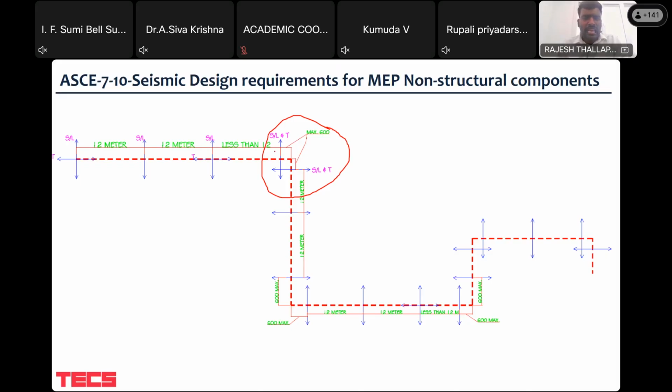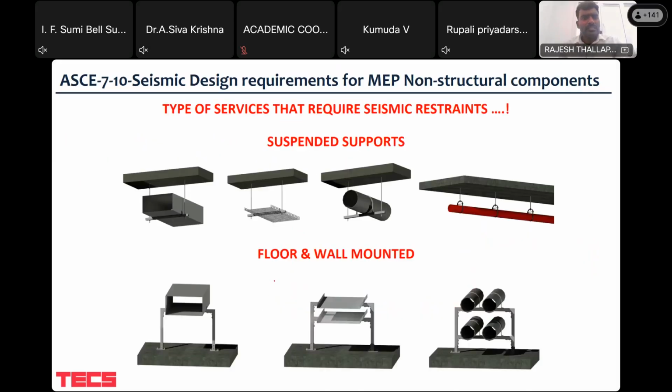So that's the reason any of the elbows are strictly need to be protected with a minimum distance of 600 millimeter, say close to half a meter. So it must be protected or it must be seismically restrained. We will see some 3D pictures or 3D applications, how practically it looks like. So these are the different components. I hope now it is more clear, where you could see some couple of 3D images.